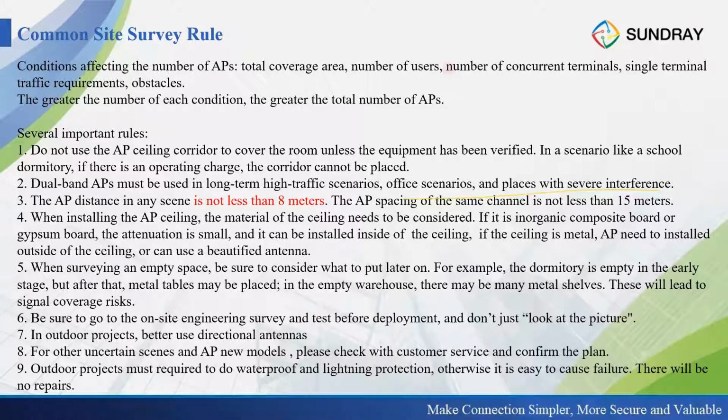They have potential risk. And for the other APs, we need to do waterproof and lightning proof protection. For example, when you finish your project, make sure that the covers of the AP's Ethernet port and console port are closed, and also that the AP's grounding wires are connected to the ground, right? This helps to extend the lifetime of our devices.